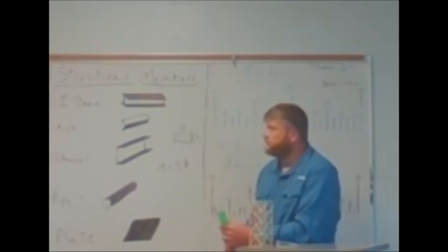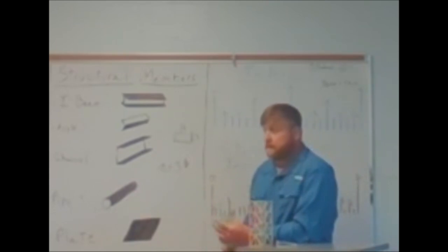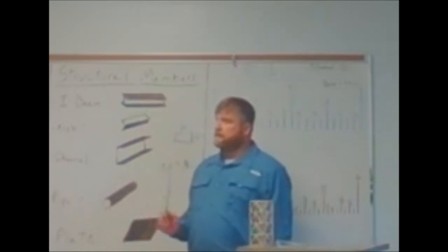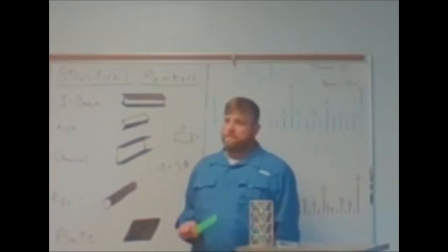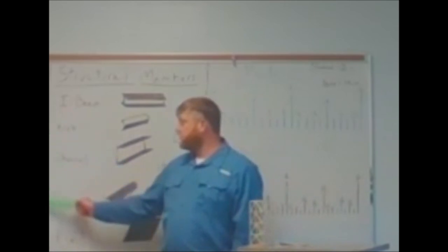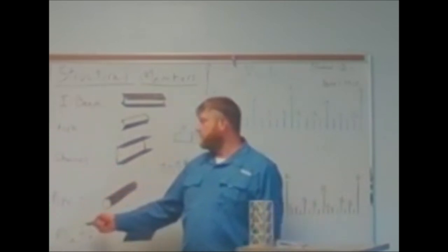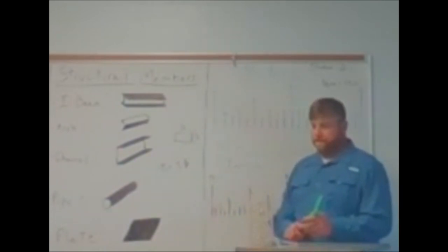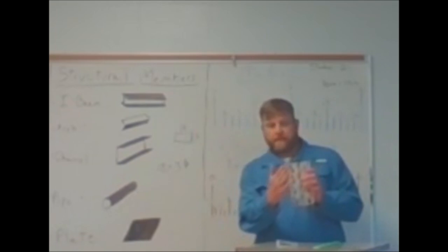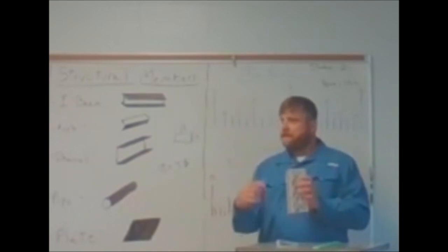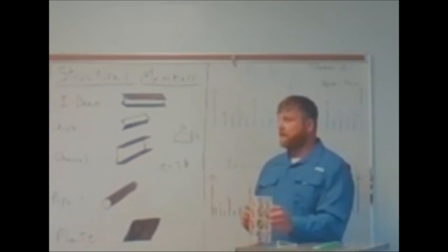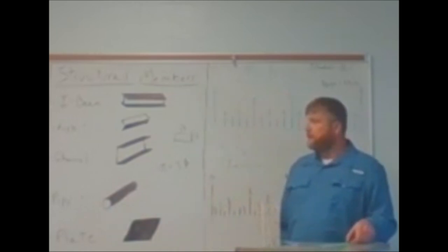What is plate primarily used for in structural design? Yes, shielding. But if used as shielding, it would not be figured into the structural integrity of the building. Let's go back to our components. Which one of these could you use plate on? Right, joints. Okay, so if you're tying all these members together right here, you take a piece of plate with holes in it, rivet it, weld it, bolt it, whatever, to tie all those joints together. Call that a fish plate or a splice plate. Okay.